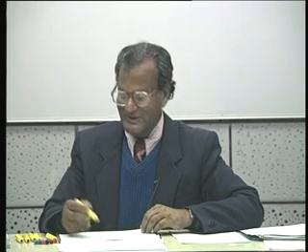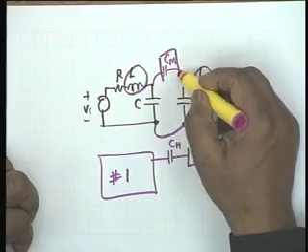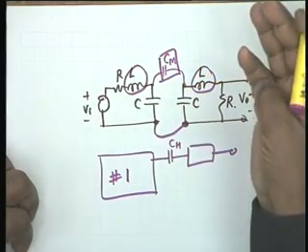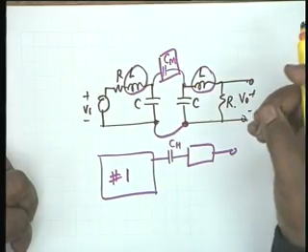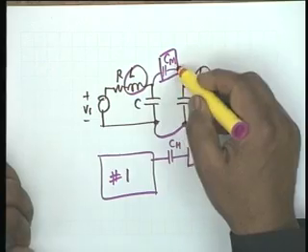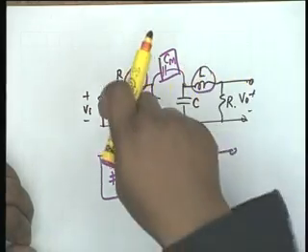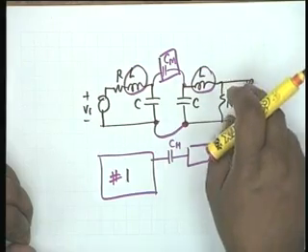Is it possible to replace the capacitor by a resistance? Of course, it is possible. Anything connected here, it could be resistance, inductance, capacitance, anything which is non-infinity in impedance. Is that clear? A finite impedance connected here is adequate for coupling two circuits, provided they have a common reference.